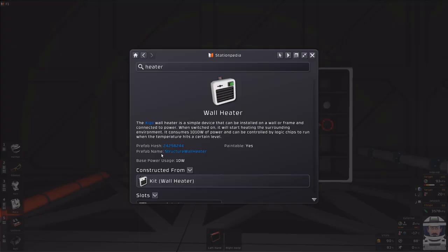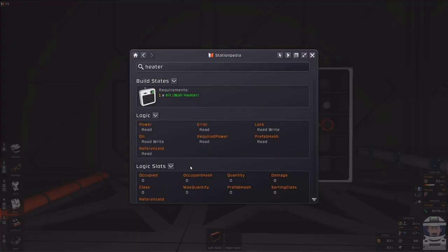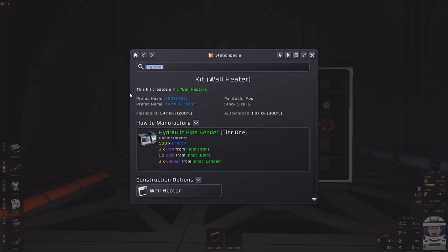They do have data connections that you can automate, but by the time you start to get to automation for these things, I would recommend that you just swap over to an AC atmospheric system. And if you're going to go really big on automation for your atmospheric controls, then ACs or phase change devices would be better in the sense of power efficiency. Yes, they work, they're simple, good to use, but definitely move on from there.